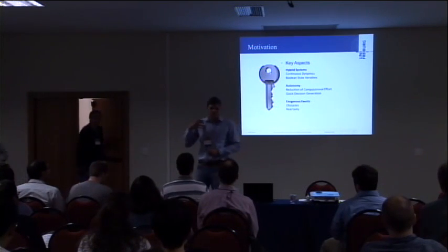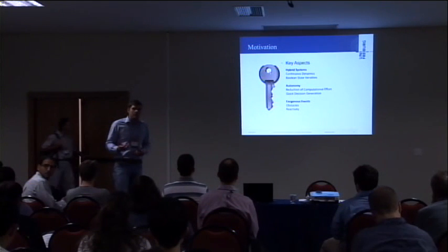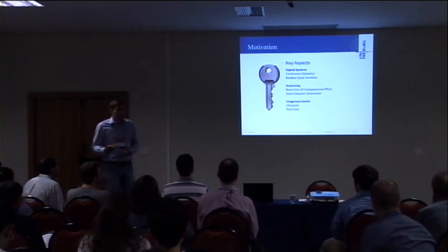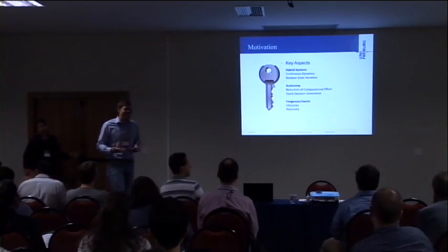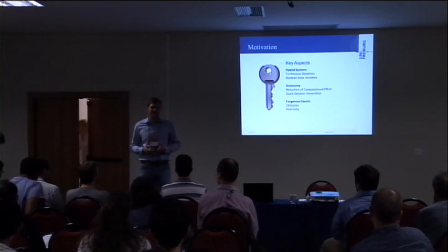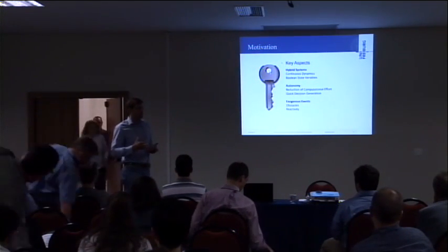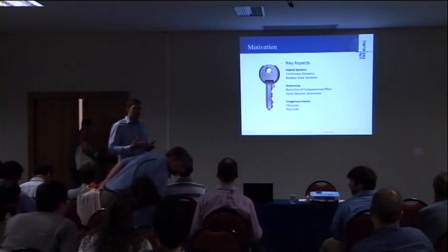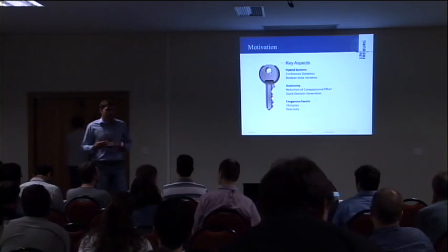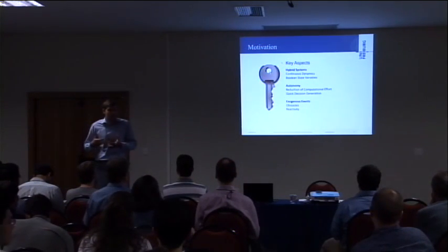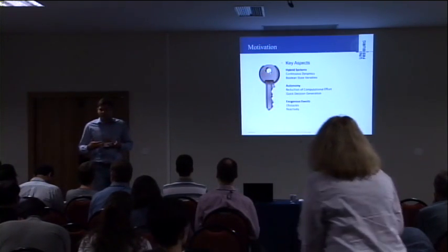And if we want to develop such a framework, we have to focus on 3 main aspects here. First of all, we have to handle a hybrid system. That basically means we have a system with continuous dynamics, which are captured by numerical state variables, and we have additional Boolean state variables, which define the mode of the hybrid system. Additionally, we want to make our spacecraft more autonomous. That means we have to do this computation on board.